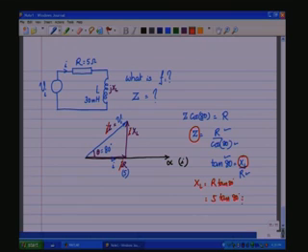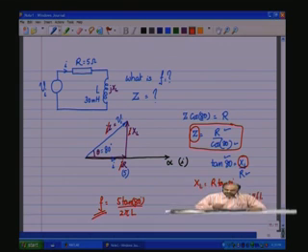This is equal to omega L or 2 pi f L, and therefore, the frequency is 5 tan 80 degrees divided by 2 pi L. L is given 30 millihenries and all else is known, and therefore, the frequency can be calculated, and Z is calculated from this equation. So, this is how we go about performing the analysis.